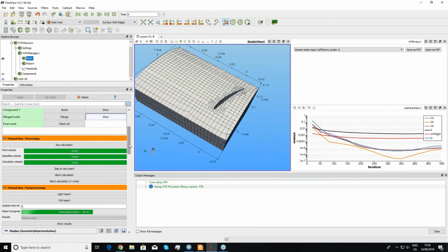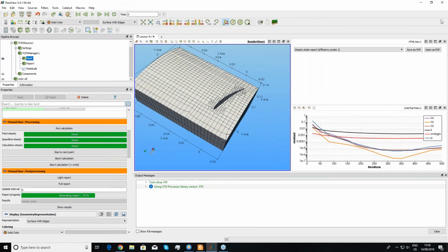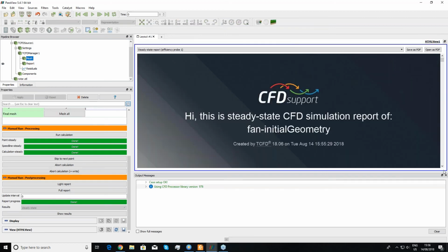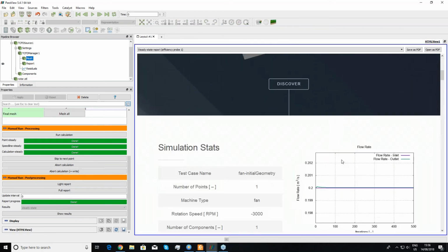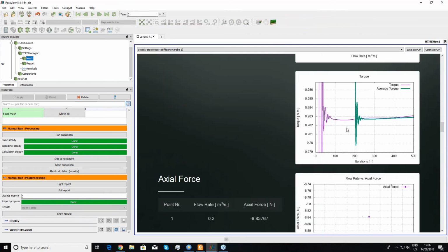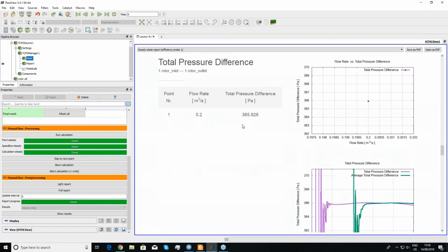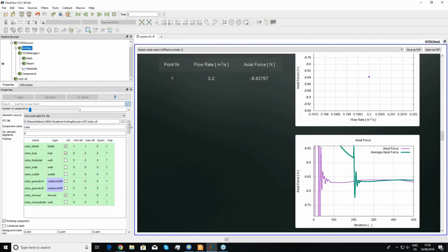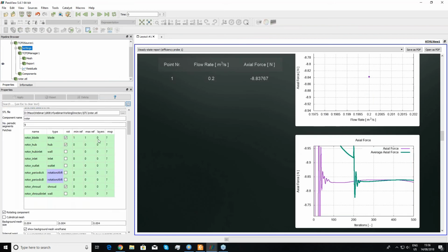I will let it finish to see then here. So whenever the report is finished, it will appear in this window, which I can enlarge. This one I can get rid of, and now you can see the progress of the simulation. So you can follow the report and do anything you want. And now, for example, I can go back and decide that I would like to simulate the blade, of course, with the layers. So I will set, let's say, 3 layers to be applied on the blade.